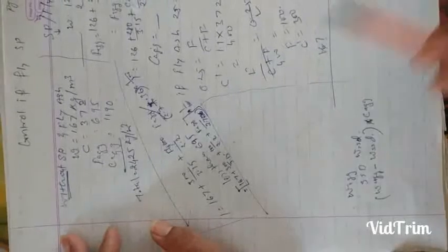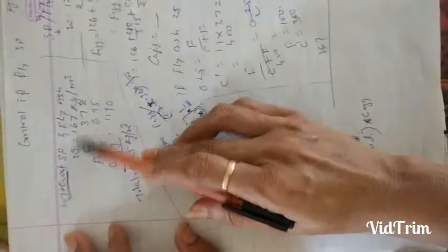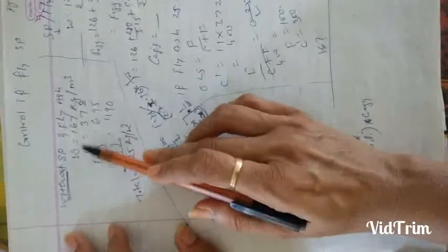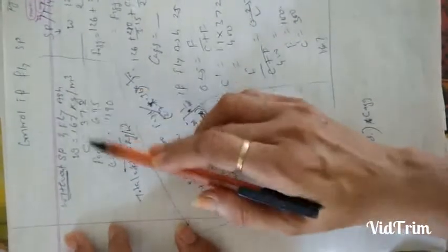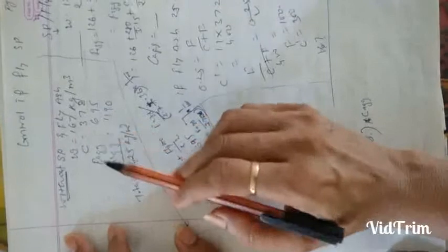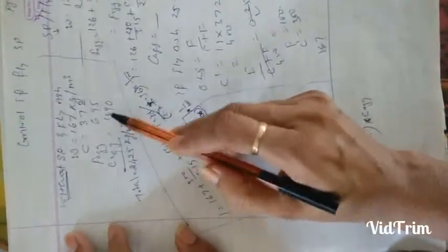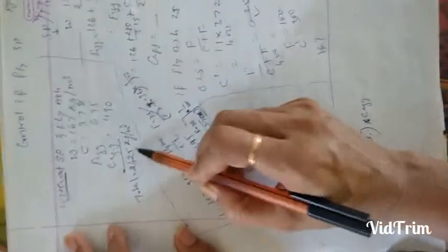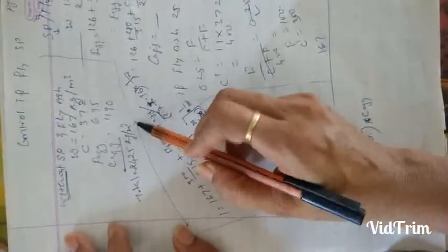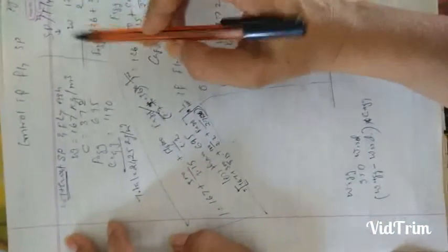Right. So now, if you consider without superplasticizer and fly ash, water content is 167 kilogram per meter cube. Cement we have 372. So fine aggregate is 695 and coarse aggregate 1190. Total is 2425 kilogram per meter cube. But if we consider superplasticizer, then W is equal to 126. We checked earlier, 126, I think.